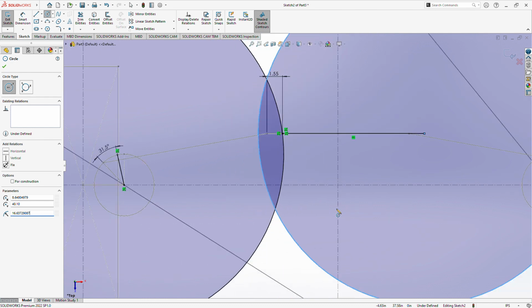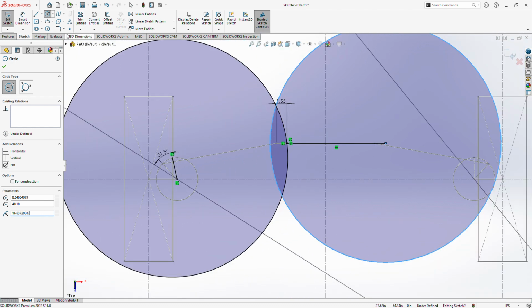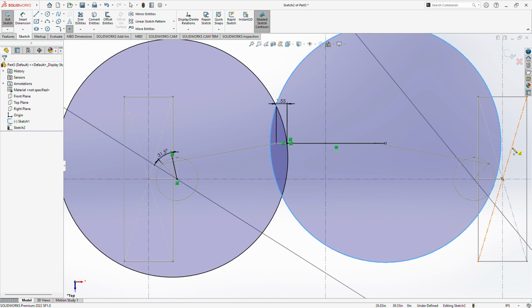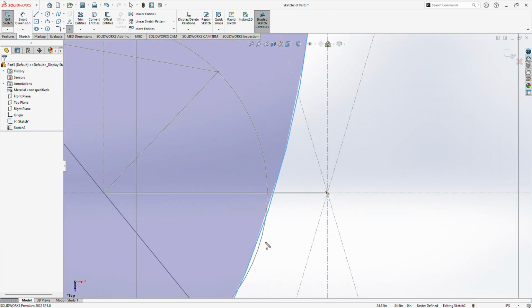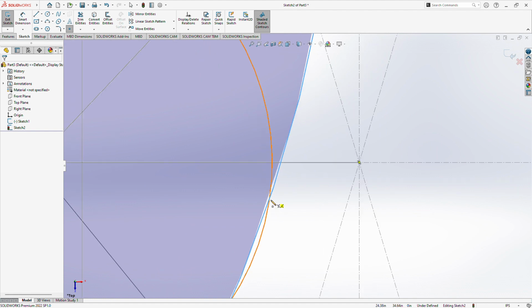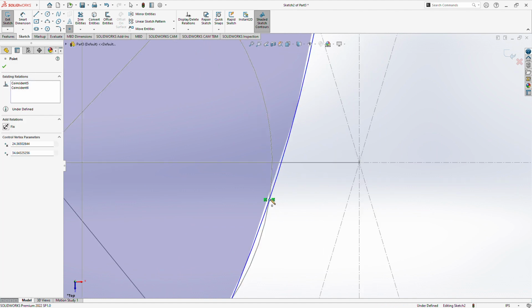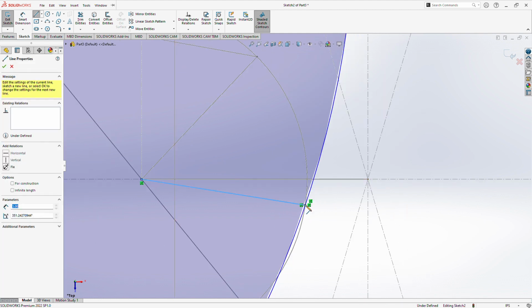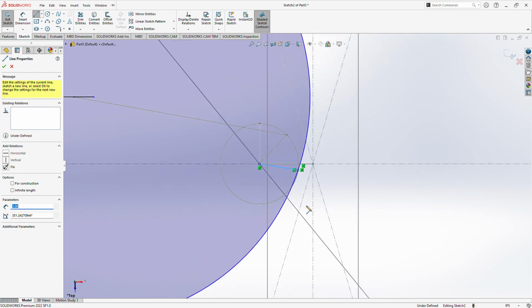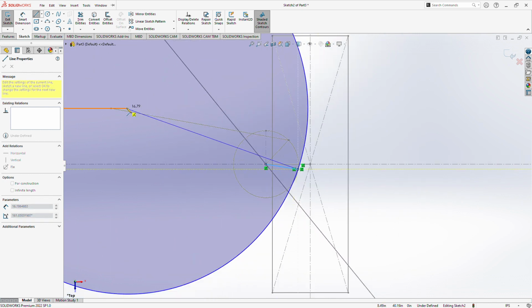Okay, mark a point where this locus of the tie rod and this locus of the steering arm intersect. Okay, mark this point. So this point will be indicating where the steering arm will end after the vehicle takes a right turn. Make the steering arm, connect the steering arm to the rack. This gives the tie rod.